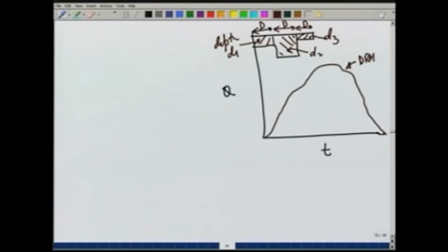And to do that, we again use the principle of superposition. So, we say that let us assume that there is a unit hydrograph corresponding to duration d, which looks like this, and it has ordinates u1, u2 and so on, which we do not know.